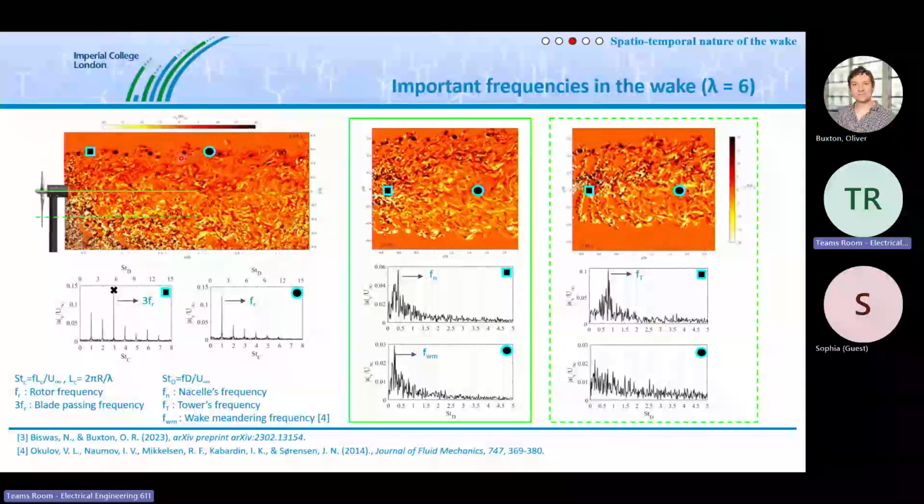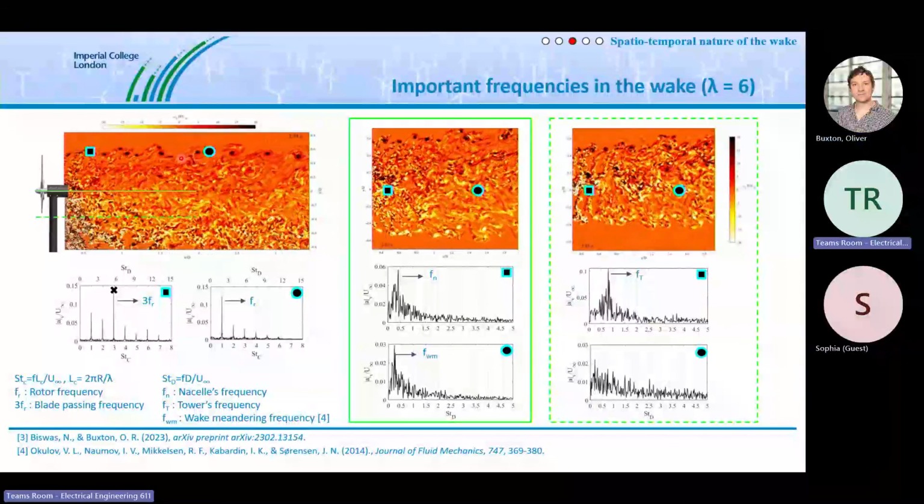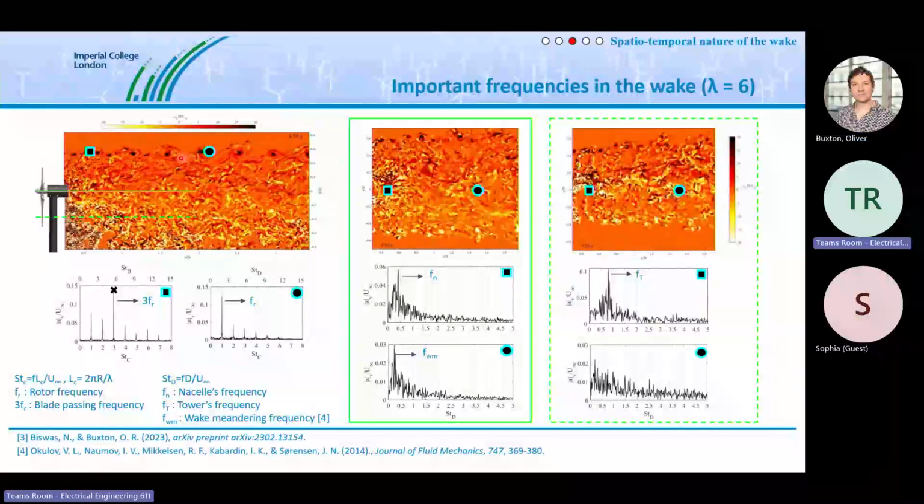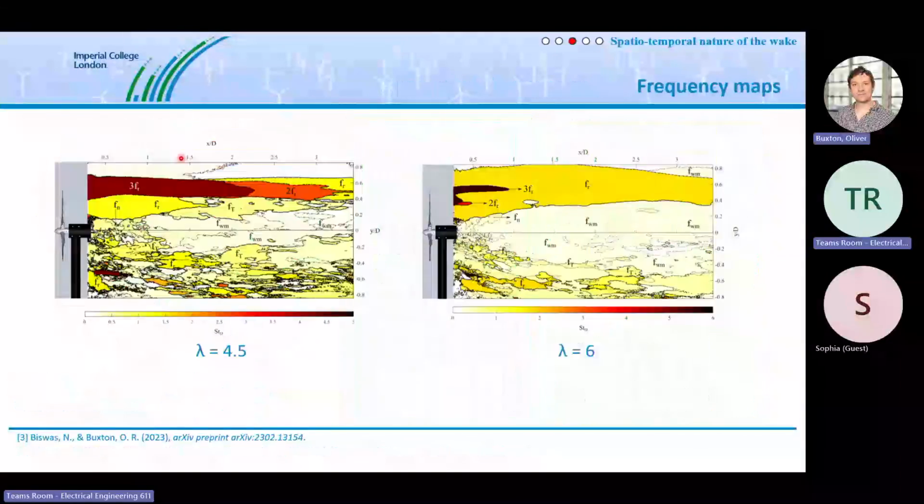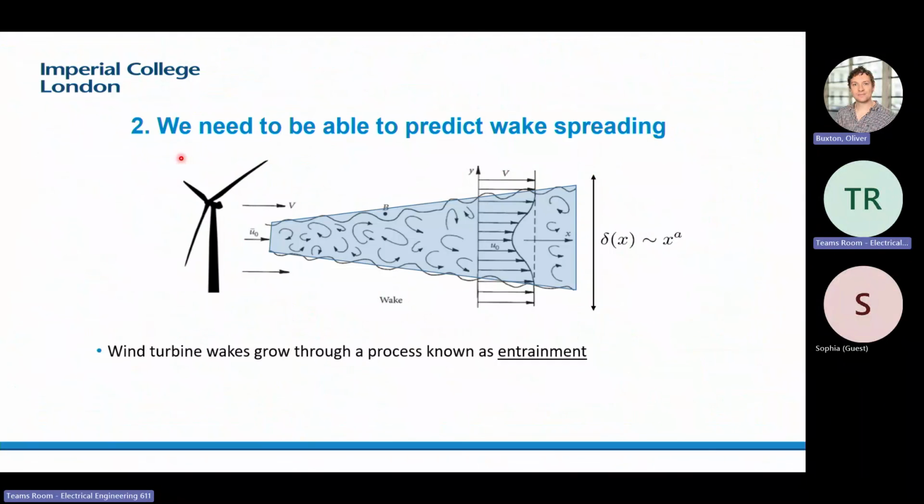Yeah, of course. And you mentioned entrainment. Do you think the effect of the tip vortices will be important? Yeah, for sure. The tip vortices are effectively promoting motion like this into the wake. So when these vortices break down versus when they don't break down definitely affects the entrainment rate. Like I say, there are two mechanisms for entrainment. There's the large scale process, which is termed engulfment, and these tip vortices are going to be very important for that.